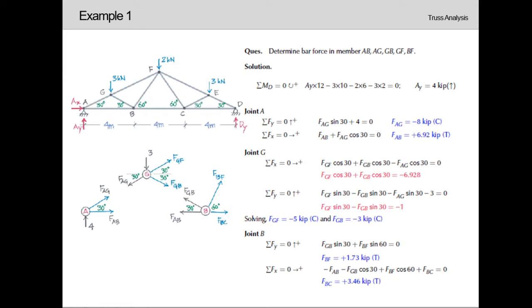So in continuation to our previous lecture, we had already learned that a truss is a two force member. That means it is only able to carry tension and compression, and the loads acting on this truss will directly be acting on the joints only. The truss member is a straight member, so it is not able to carry any moment. Moreover, we have also learned that the forces will be acting away from the joints.